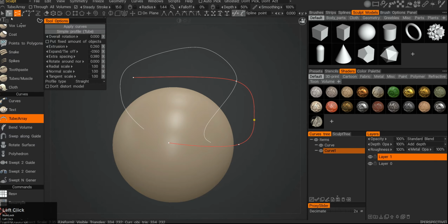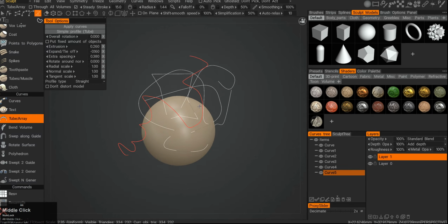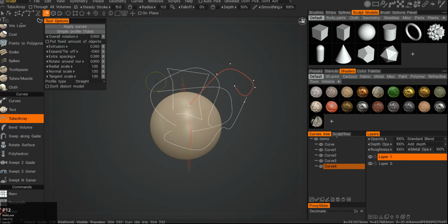Then these are the curve creation buttons there. I can create a really linear curve. Then the one I've been using is a smooth curve, and then we have a Bezier curve, which allows you to modify the points. If I right click, I can make them different: smooth, angulated, and all that. Then I have a kind of lasso drawing tool, so I can free draw the curve. Then we have an eraser. It allows us to erase parts, and then each individual part will become its own curve.